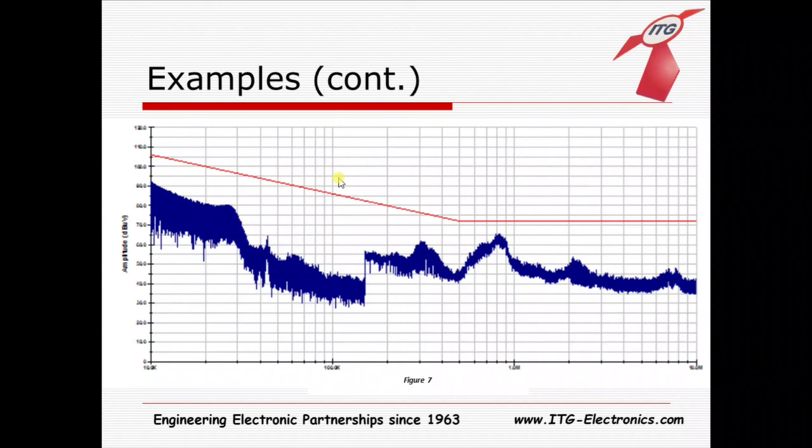So if you're going into a situation where you may have to be doing some testing, you may have to increase your filtering. It's always a good idea to leave some longer leads on those common mode chokes to potentially increase the inductance. Obviously, you don't want to have extra long leads on a final product, but if you're doing some testing or something like that, it's a good idea to keep that option available so that your solution can come quickly while you're in the lab, because lab time is expensive.